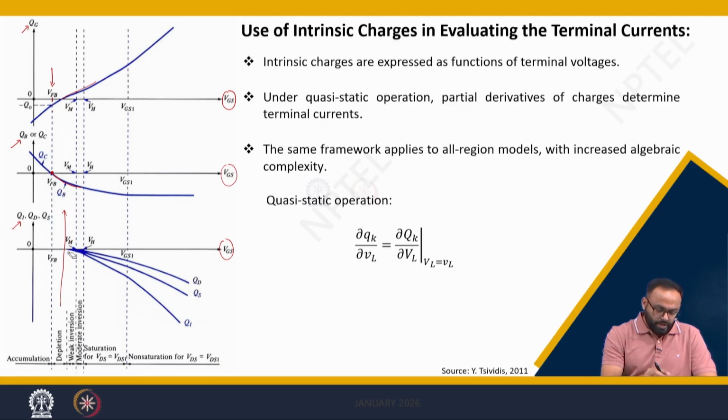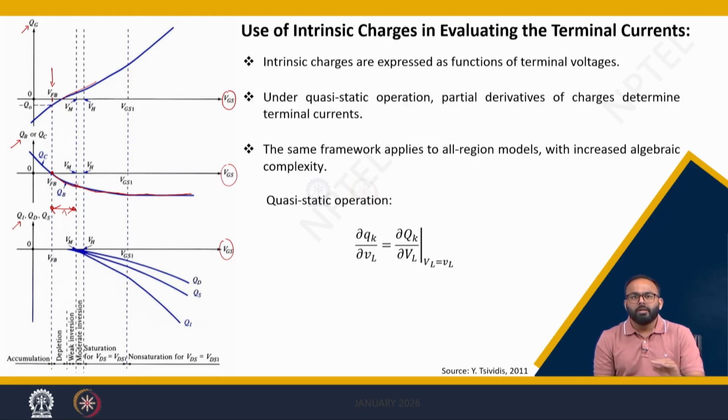So ultimately these 2 points show the weak inversion and depletion region of operation. Now when you increase VGS, the depletion charge or bulk charge continuously increases, but at a certain point it will become constant. That is what we have discussed. In non-saturation region of operation, almost uniform depletion region will form, right? That is why the depletion region charge becomes constant when you enter into non-saturation region by increasing VGS.